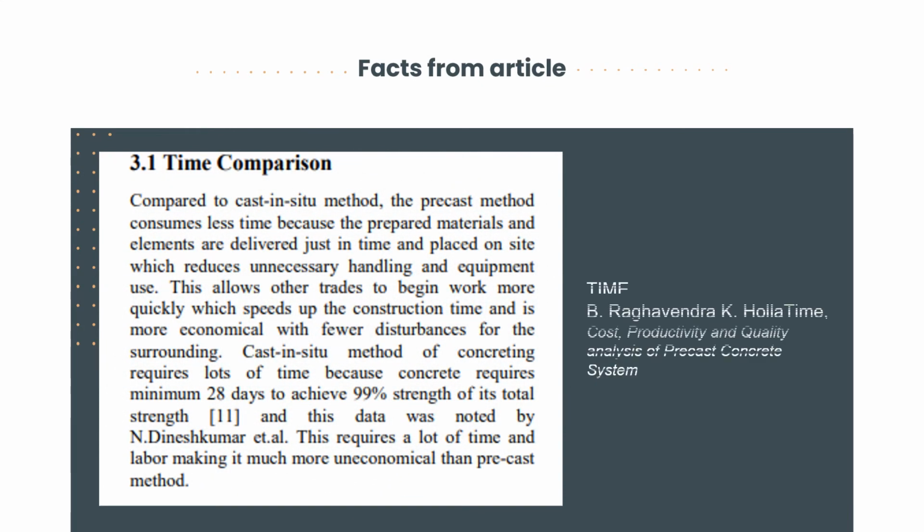All our justification can be proved by facts from articles. The first article is stated about the strength. In the first article, it says that precast concrete buildings are often more durable. This is because, compared to cast in place, precast has a longer lifespan and service period. The second article is a comparison between the costs of precast and in situ, and the article says that the cost of precast is less than the cost of in situ.